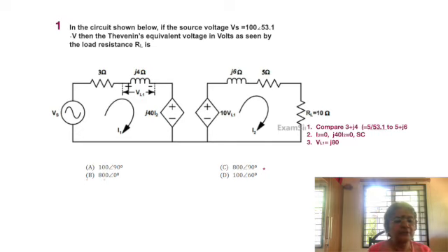The one on the left is j40 I2, where I2 is the current in the second loop, that's in the right loop, and both these loops are now joined together only via a single line, or in other words, they are independent with respect to each other, except for the fact that they have the same reference. Okay, this I've been repeating several times. Similarly, let's move on to the next dependent source, which is 10 VL1, where VL1 is the voltage across the inductor with a reactance as given by j4.